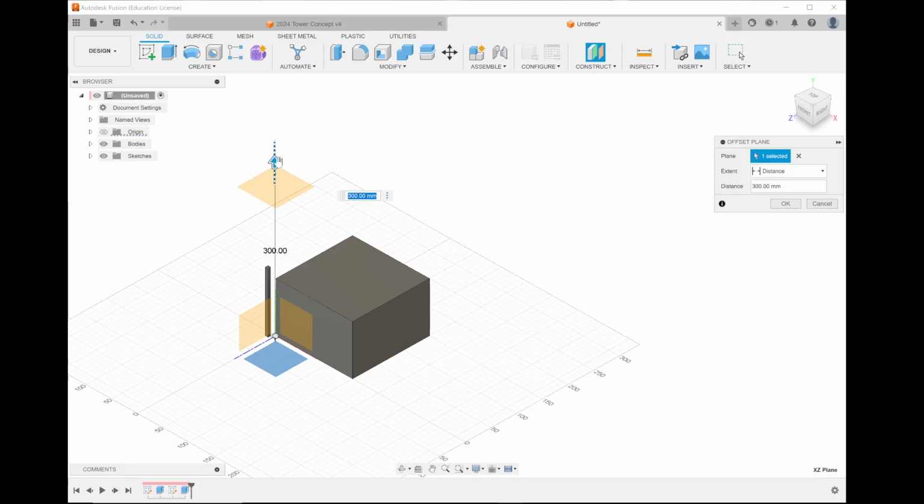At least 30. So for my design, I'm going to put 30. You might put 30.05, right? Give you a bit of safety. But also for this technical drawing, you can do 30, it's fine. So 300, right? Because we're dealing in millimeters. But you did say 30. 30 what? Centimeters. Fusion is smart enough that if you write 30 centimeters, it will automatically do that.